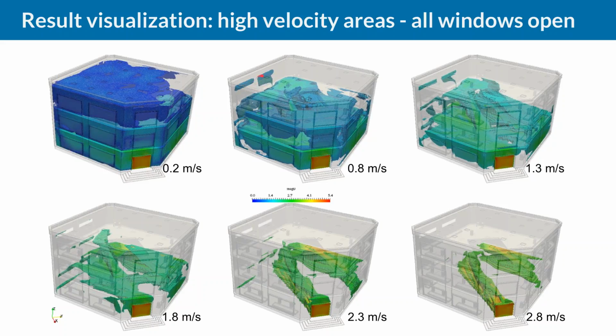It's really blue, and so all the air speed here is somewhere around 0.8 meters per second, while for this large opening and some of the windows on that side, on the second and third floor, we have much more wind going in and out.